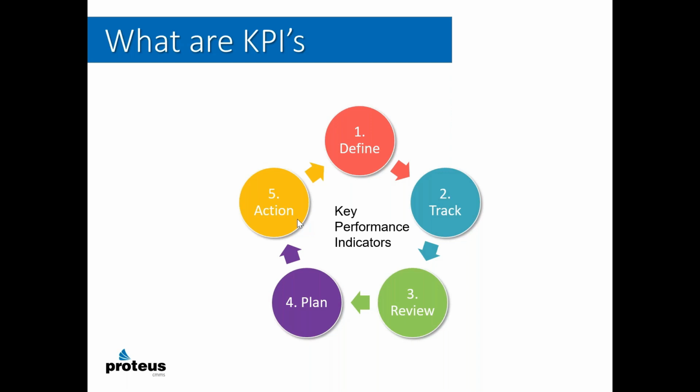In a hospital environment, I had a client that measured hot cold calls. The first time, the technician went in and assumed that it might be a thermostat problem, so they replaced the control on the wall for $75 or $80 and assumed that the problem was fixed. The next time they get a hot cold call to that room, it's critical that the next technician realize that somebody did the replacement of the thermostat.